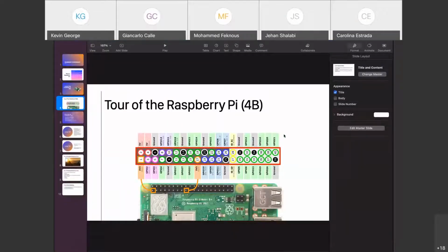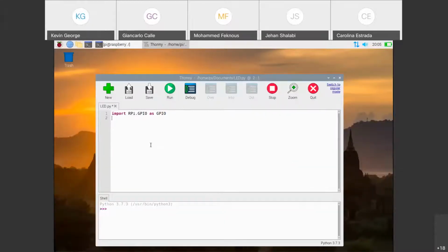So we're going to be manipulating this piece of hardware on the Raspberry Pi to manipulate our LED. In Python, we import our libraries so we can use them. Our library is going to be called RPi.GPIO, for general purpose input output. We're going to be calling that into a variable GPIO. We're also going to use the time library so we can do a little bit of timing with our LEDs. So import time.